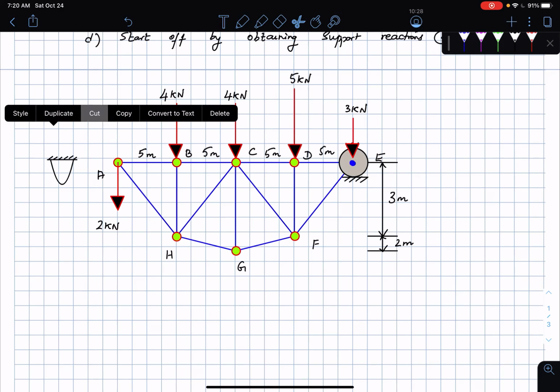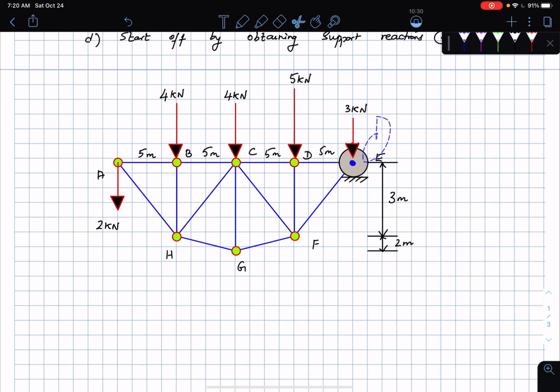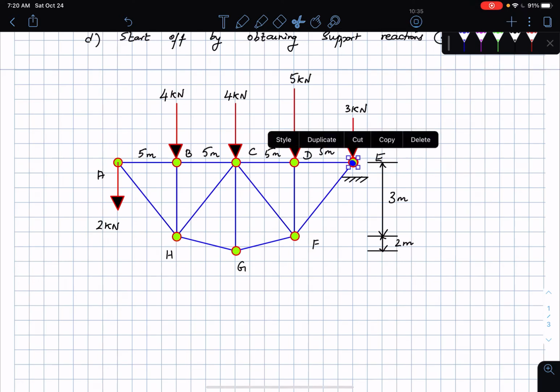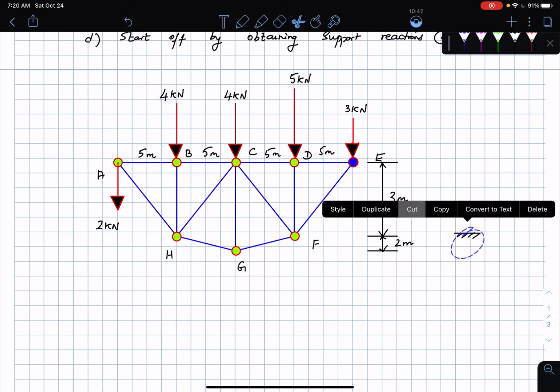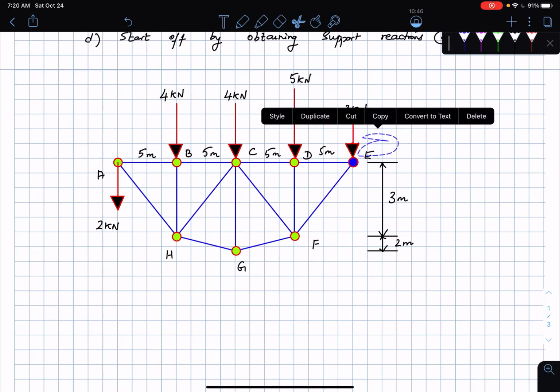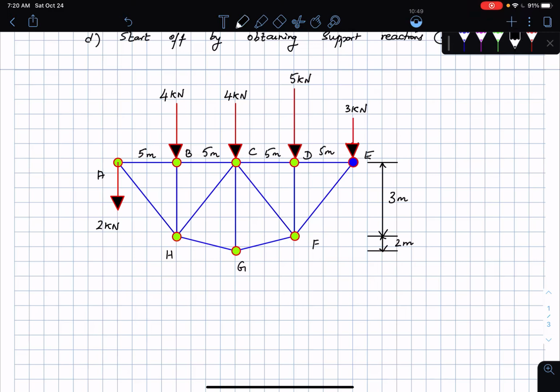be showing any of these things, right? I'm not going to be showing any of those things either. Okay, so I'm going to be cutting that off, and probably I don't need that either. So this is the situation that I have. Instead of showing the supports, I show the effect of the support at these different points. Okay, so in this case I'm going to have reaction forces at the pin A. Let me draw it, and I'm also going to have a reaction force at E. So I'm going to have a roller reaction which I'm going to point upwards here. So I'm going to call it EY.